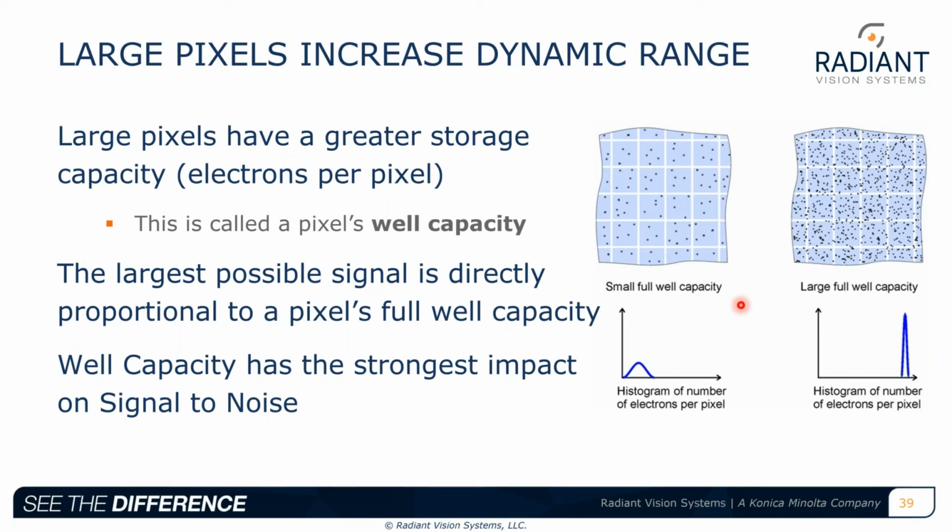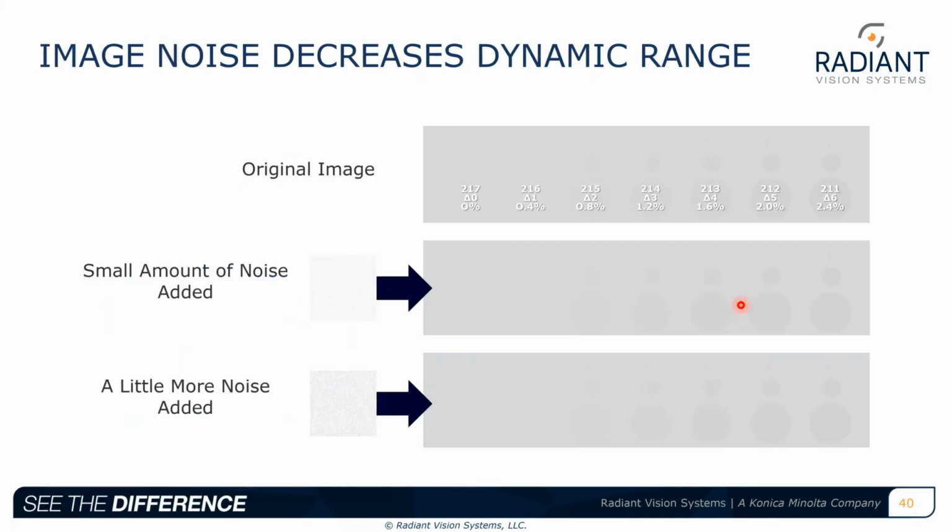So that is important to keep in mind. The reason that we bring this up is that sometimes dynamic range and resolution go head to head. So let's say you have a CCD that has pretty big pixels and you want higher resolution. Why don't you just take each of those pixels and cut it into 4? That would increase your resolution, but then your well would be smaller, you'd have smaller pixels, so you'd get more noise. So really it's a trade-off between getting high resolution, but also making sure that your pixels are still large enough that you get the dynamic range that you need.